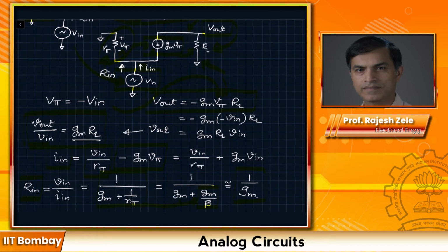And this is the example where if you need a 50 ohm termination looking into an amplifier, then we can use this particular amplifier. The output resistance of this particular amplifier is going to look like, again, over here it's RL, assuming Rout is very large. Similar analysis like what you would do in common emitter case.